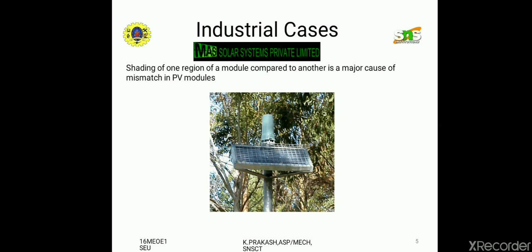The band gap of the semiconductor material is reduced with an increase in temperature. Most of the parameters of semiconductor materials are affected by the increase in temperature. By increasing the temperature of a semiconductor material, the energy of the electrons in the material will increase, so that to break the bond, lower energy is needed. The reduction in the bond energy also reduces the band gap. Hence, increasing temperature reduces the band gap.